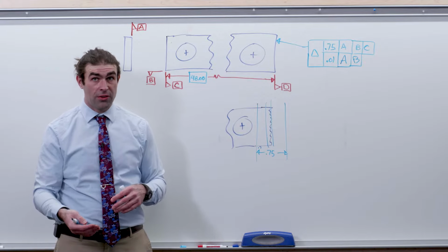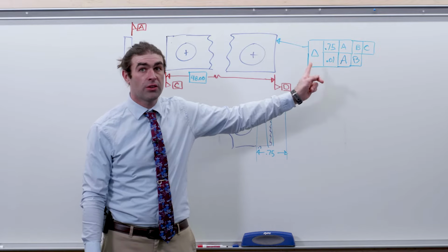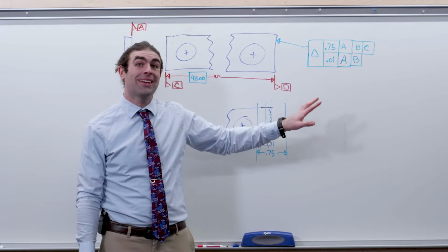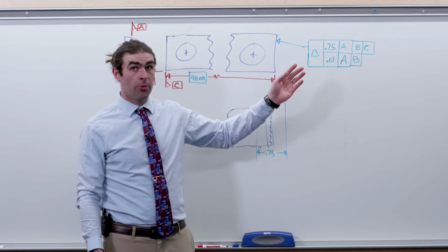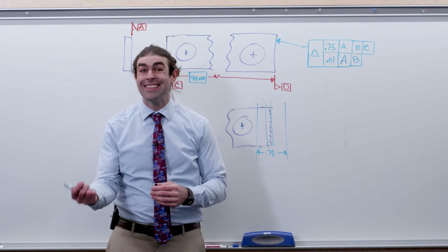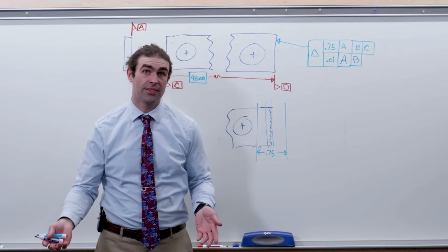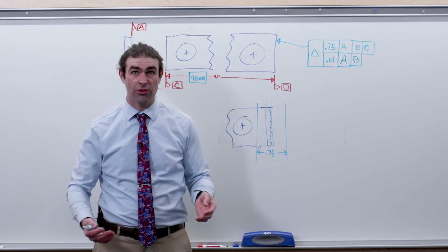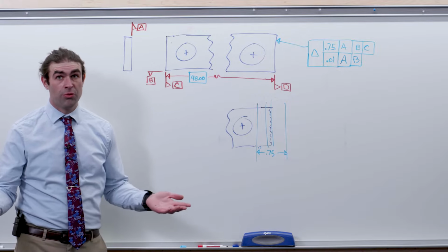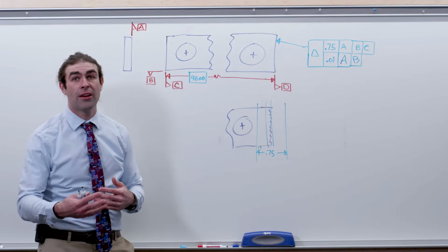Now, another thing I want you to take from this is that when you see a complicated feature control frame, it often means that you have more tolerance because the designer went through a little bit of trouble to figure out where to get some extra tolerance from. It's the easiest thing in the world to slap a profile of 10 thousandths to A, B, and C, or your primary, secondary, and tertiary datums on your part onto a drawing, and that is normally good enough. But if you have this, it meant the designer went out of their way to find some tolerance.